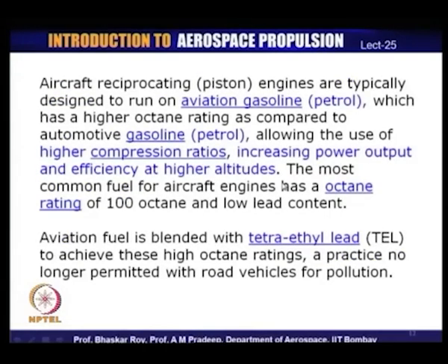A word about the fuel. Some of the fuels that are used in typical aircraft engines are basically petrol based. In some parts of the world, they are also called gasoline. They have, as I mentioned, a very high heating value, that is how they are chosen, and quite often they are to be used under high compression ratios. We need to have high power output, and of course, as we have just seen in the efficiency definition, good efficiency at various operating conditions of the aircraft, most specifically at high altitudes where the aircraft actually flies.